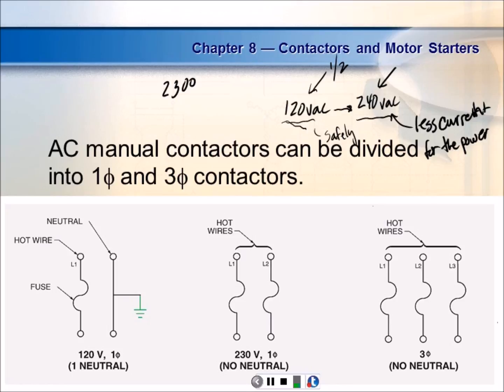So if you take your dishwasher, if you got one of those, it's designed to run off 120 volts, and you decided to wire it up to 240, what's going to happen is you turn it on. All the electronics in there is going to burn up, right? Everything's going to burn up, because it's going to try to consume 4 times the power than what it was designed to do, right?